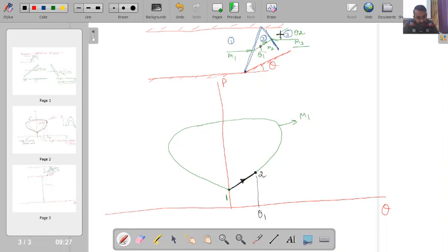In another sense, this point 2, which is at an angle theta 1, will act as the starting point for this second wave. So my pressure deflection diagram will now start from point number 2, and it will be for Mach number M2, which is less than M1. So now the overall origin of my diagram will be lower.